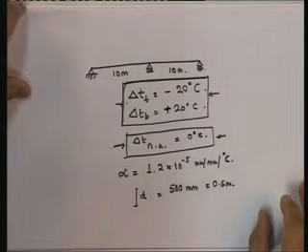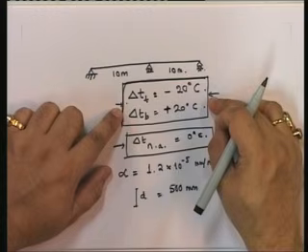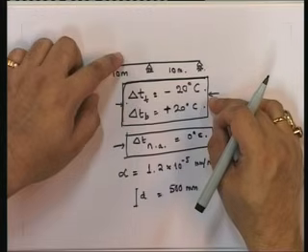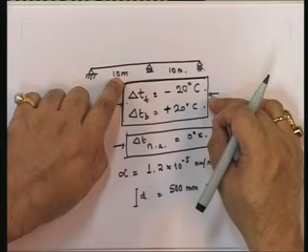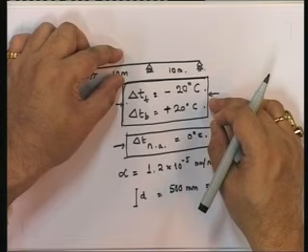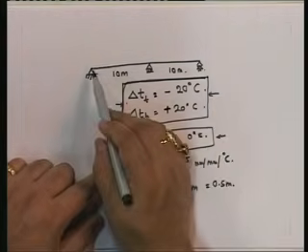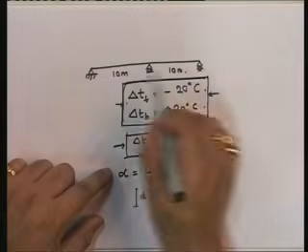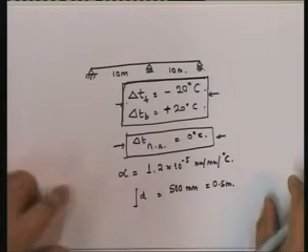Okay, so therefore the problem statement here is due to this differential temperature, where the top is minus 20 degrees and the bottom rises by 20 degrees. So there's a temperature differential of 40 degrees between the top and the bottom. What would be the forces in the supports and the bending moment diagram for this statically indeterminate truss?